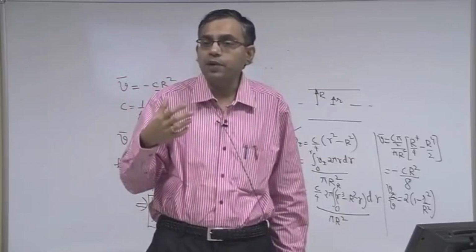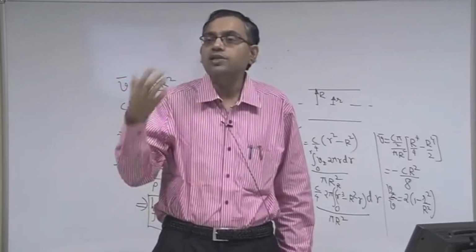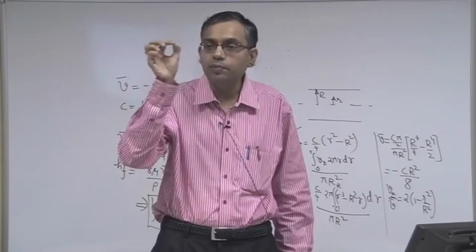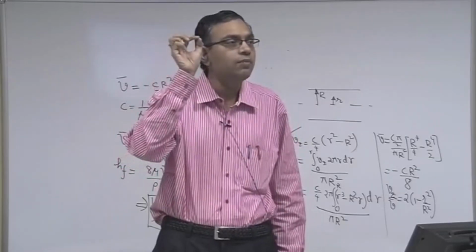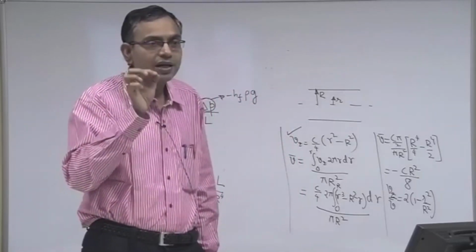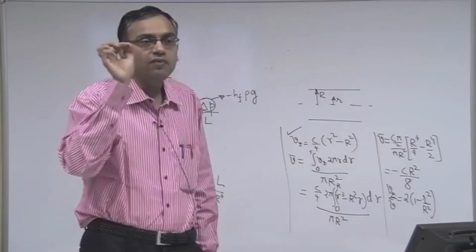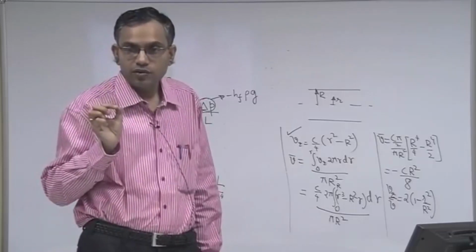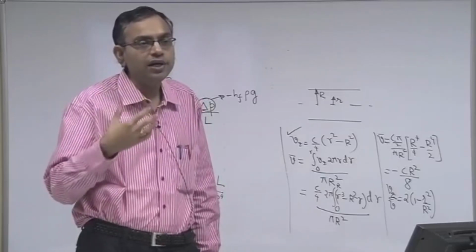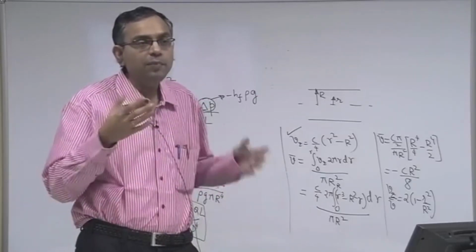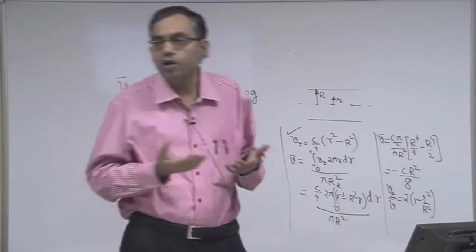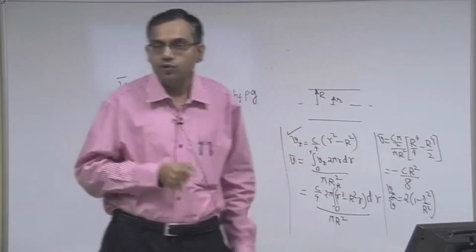Not in all applications you require a large Q. For example, you are administering a medicine or a drug to a patient in a very minute and precision quantity. So there you do not require a high flow rate. There in fact a precise delivery of the drug is what is important. So high flow rate may appear to be an important and useful thing, but it depends on the context where other factors may be more important than high flow rate.